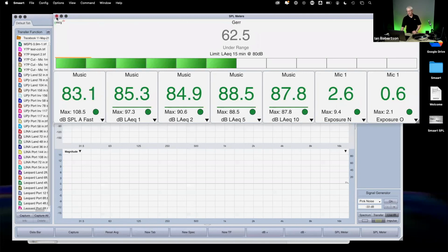So that's the last part of the puzzle, is integrating this in. The other thing about this application is that it's calibrated and traceable. So if you're doing log files and pulling in data for loudness in a venue, SPL in a venue, and someone does take you to court and makes a claim, the data set coming from this will hold up if you have a level 1, class 1 system. That data will hold up in court, as opposed to this, which I may have calibrated improperly. This can't be fiddled with.